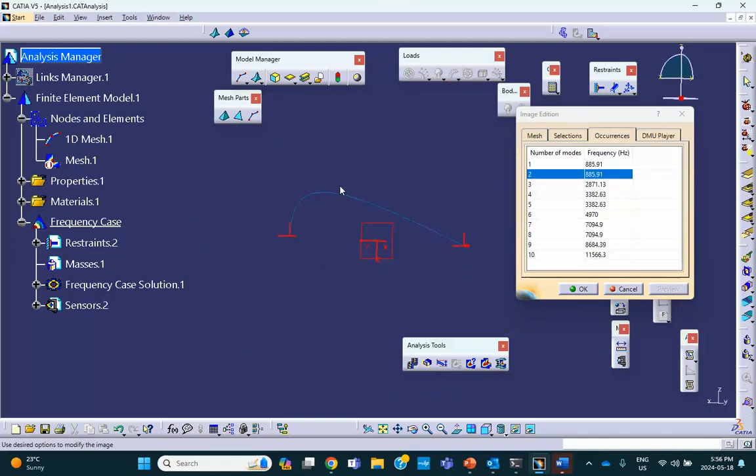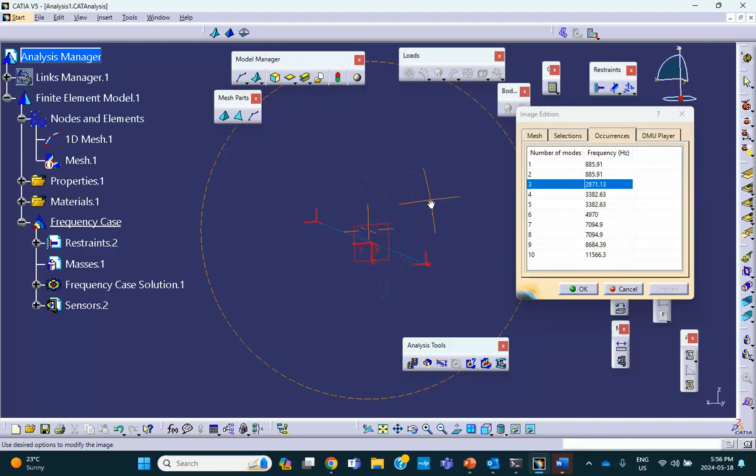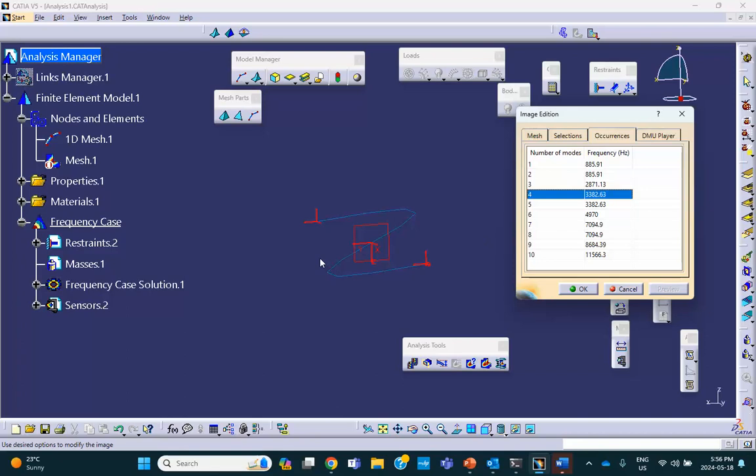And then there's other stuff here. This one is axial, probably axial vibration like that. And then there's some that are out of plane, second mode, etc. But this is the key. You compare this with what we got with the solid element, pretty much on the dot. Very few elements, 10 elements, 11 nodes, whereas in the other one we may have had 5,000 nodes or something like that. And the result didn't significantly change.